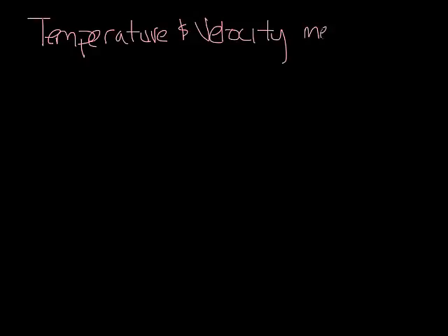Let's start with measurement. ASHRAE Standard 113, Method of Testing for Room Air Diffusion, defines the process in detail, but basically you start by taking temperature and velocity measurements throughout a room. Using these data points, you calculate the effective draft temperature of each of the points.